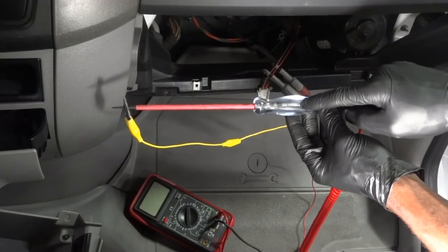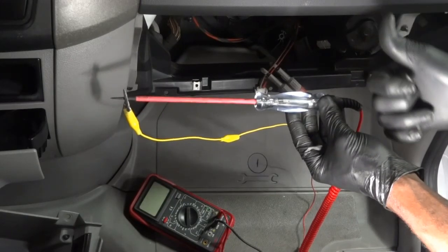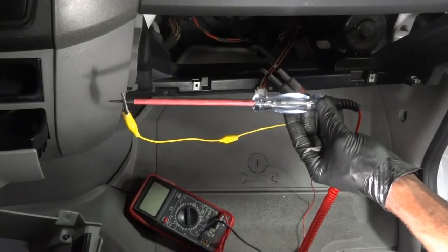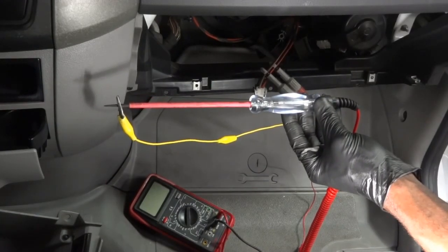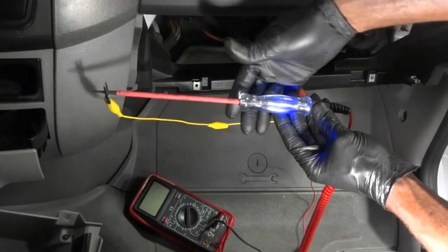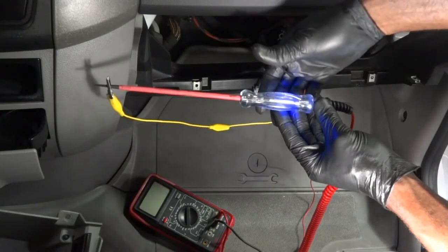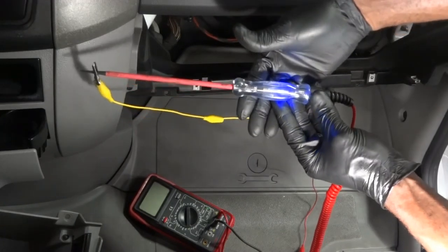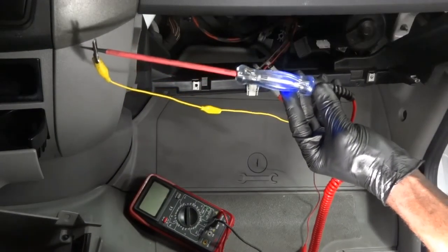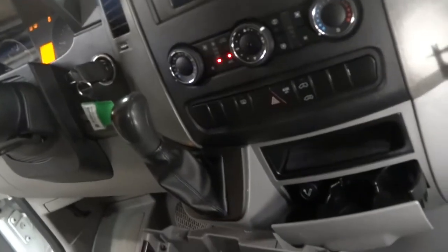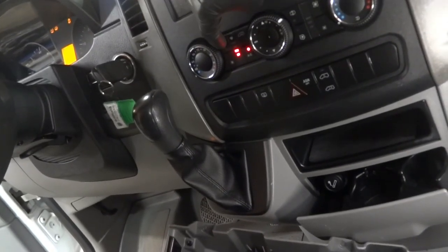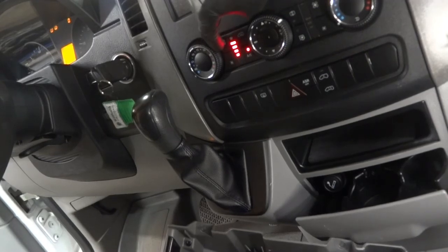If the test light lights, we know we have good power, good ground, we have current flow, so our issue will be the blower motor itself. So now I'm going to turn it on. I don't know if you can tell the difference already, but once this test light comes on, it's going to turn blue, and right here it's blue already, and it's a little bit dim. Right here I am turning on the blower motor speed. Once I increase the speed, our test light should get brighter.